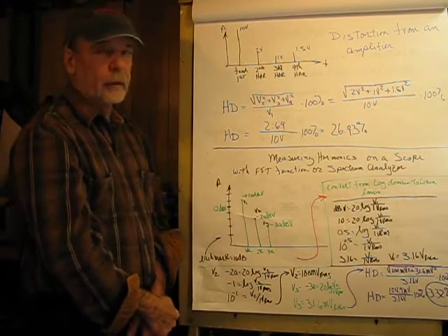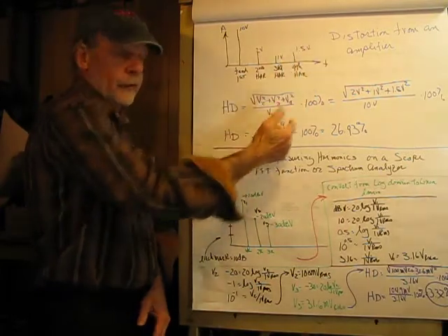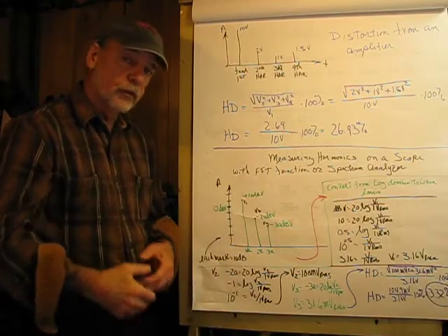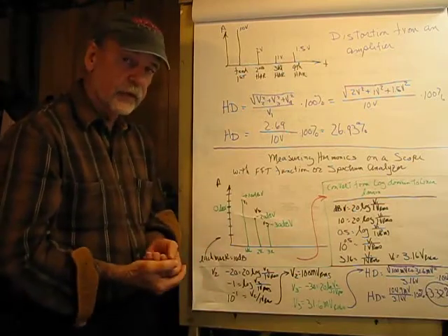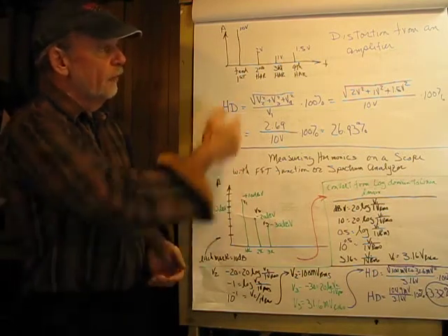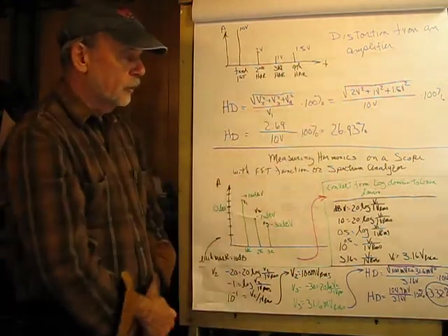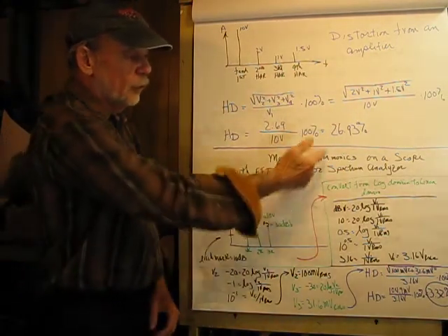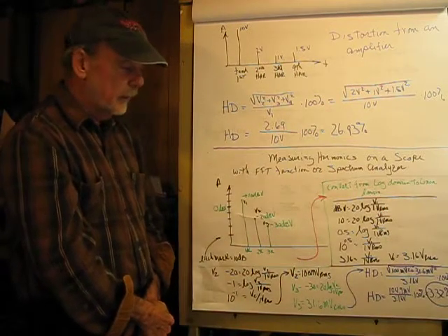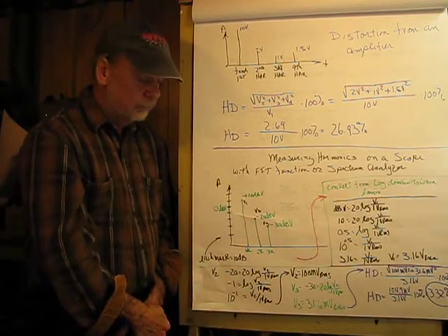Now there's no rule that says that these have to be decreasing. They can increase, and do, depending upon what the signal is, what the amplifier distortion is, things like that. So to find out what the HD is of an amplifier which would have that output signature, if we just plug in the values and work the math, we see that comes out to be 26.93%, which is terrible. Would not want to listen to any public address system with that kind of distortion.